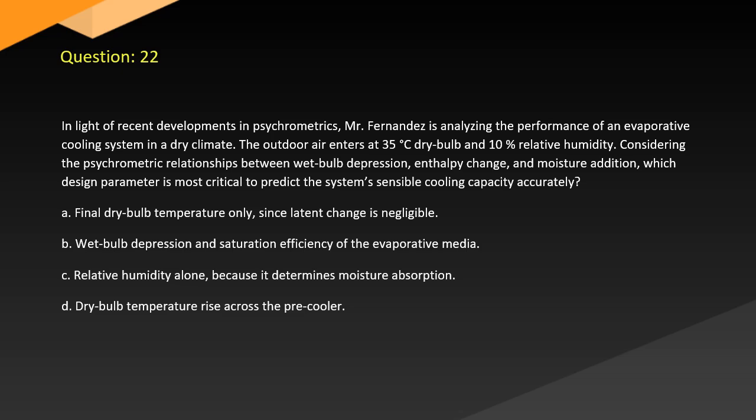Question 22. In light of recent developments in psychrometrics, Mr. Fernandez is analyzing the performance of an evaporative cooling system in a dry climate. The outdoor air enters at 35 °C dry bulb and 10% relative humidity. Considering the psychrometric relationships between wet bulb depression, enthalpy change, and moisture addition, which design parameter is most critical to predict the system's sensible cooling capacity accurately?